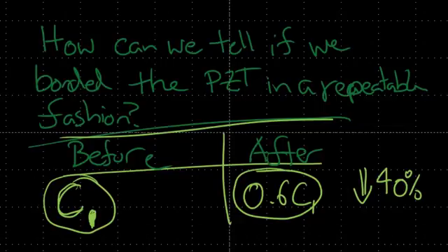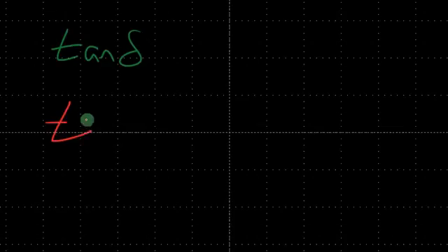We basically see the capacitance before and after, and we test that for different piezoelectric materials which have a similar capacitance before. By comparing that, we can tell that yes, the bonding is the same, because the only thing changing the capacitance in this case is the bonding. What would also be very cool is to look at the dielectric loss, because now that you bonded it through epoxy, which has much larger losses than piezoelectric materials themselves.